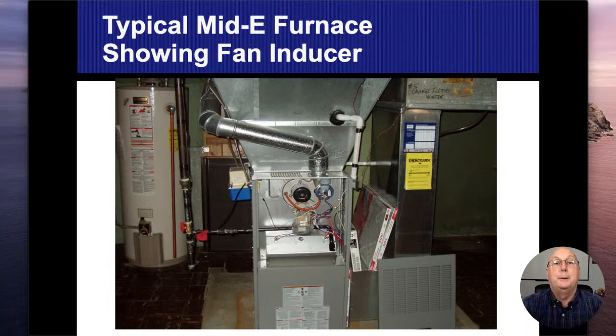All right, here's our typical, again, mid-efficiency furnace. So my inducer housing fan is made of metal, and my vent connector is also made of metal. Now, if you notice that down here, and this is a typical thing that we see, the vent connector, where it enters the furnace, it shrinks down in size.